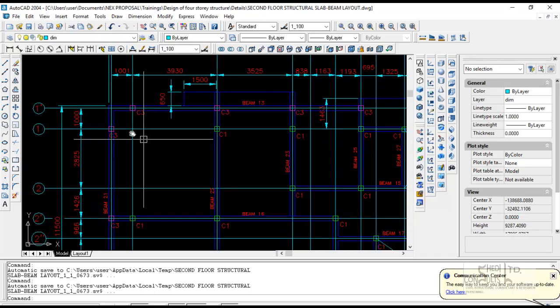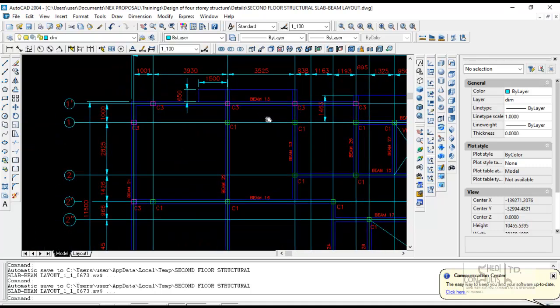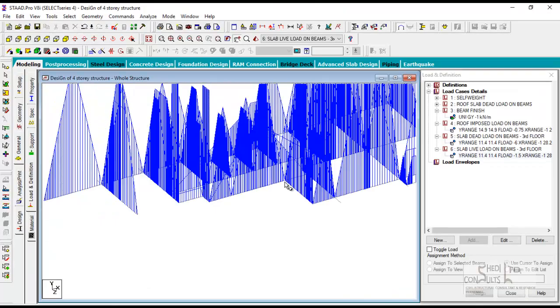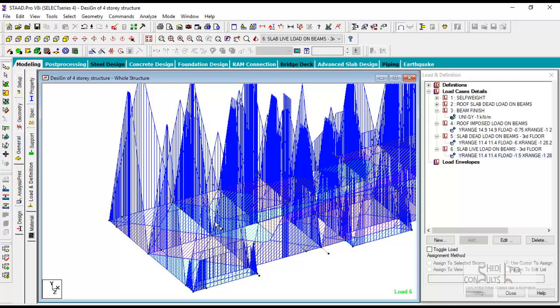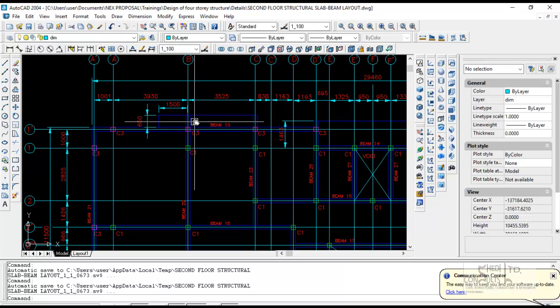So what STAAD calculates is the loading from the internal slab. Because loading from this slab on this beam comes from here to here, and from here to there, STAAD can compute that intelligently. However, if you look here where we did not model the cantilevers, you may want to compute the dead load and the live load and then get the reaction associated with that.